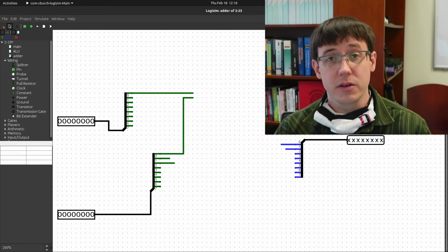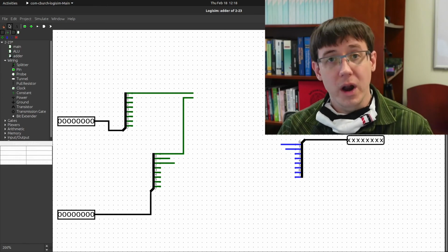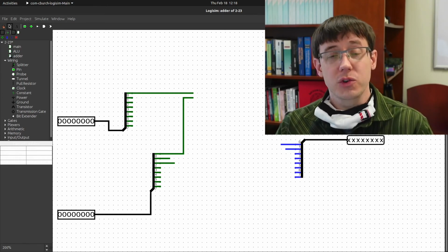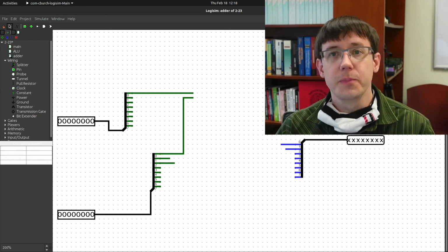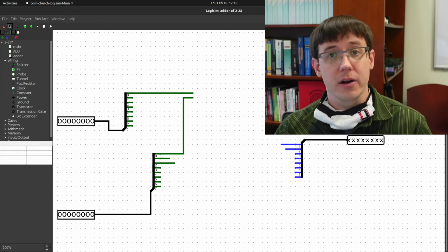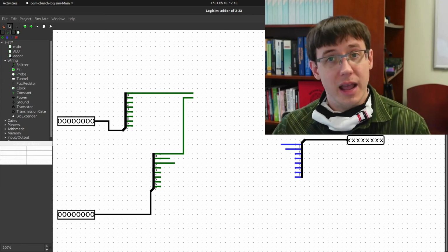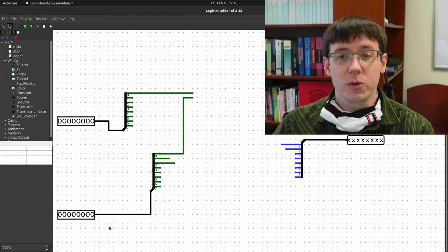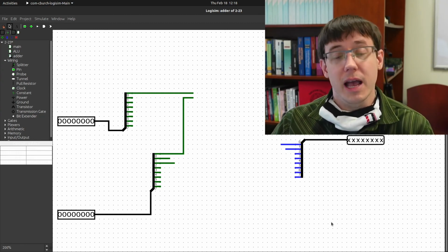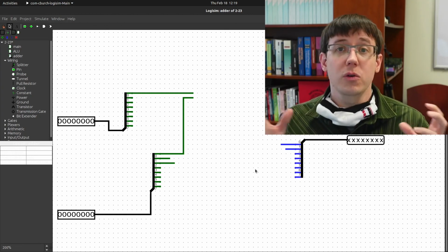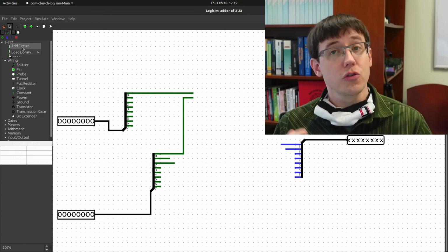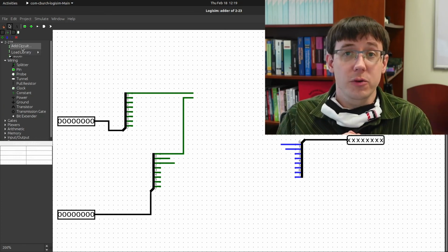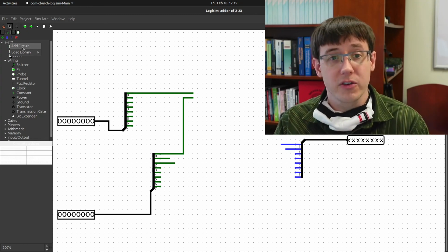In the in-class activity, you'll start by building a half adder, which adds 2 1-bit values. Then you'll use your half adders to build a full adder, which adds 3 1-bit values. Then you'll combine multiple full adders into a multi-bit adder that you can use for this adder circuit as a part of the ALU. So when you do this, it will be very helpful to add additional circuits that you can treat as subfunctions that let you think at different levels of abstraction within the circuit.